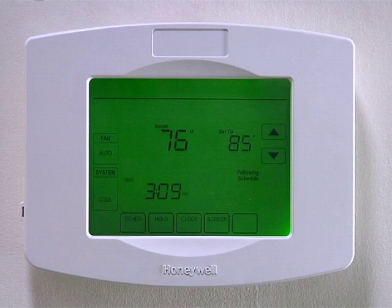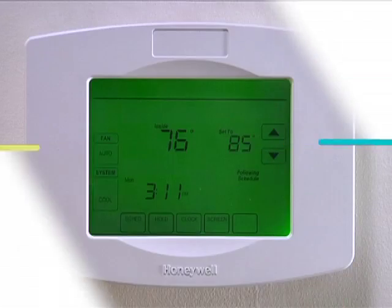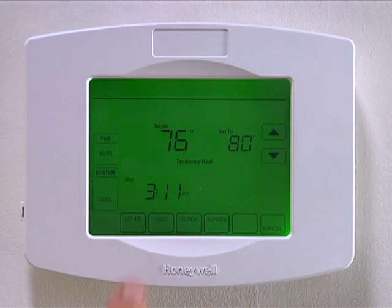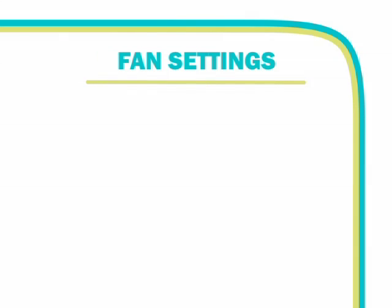To permanently override the programmed schedule, set the smart thermostat to the desired temperature and press Hold. This will turn off the programmed schedule. Whatever temperature you set will be maintained until you manually change it or press Cancel to return to the programmed schedule. The fan can be set to the following settings.